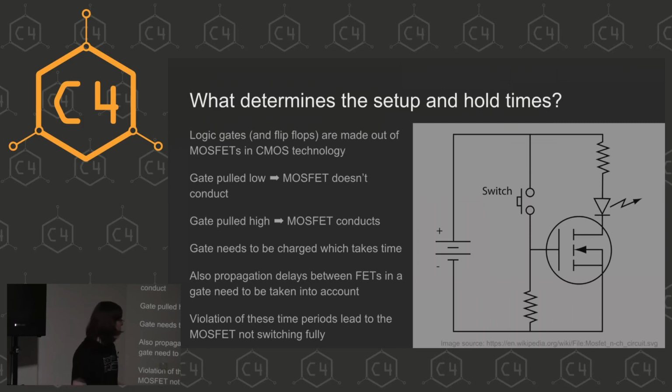Oh yeah, and if we of course violate these periods, then this thing might not turn fully on or not at all, and the LED might only be half on or something like this. So the MOSFET doesn't really do what we expect anymore.